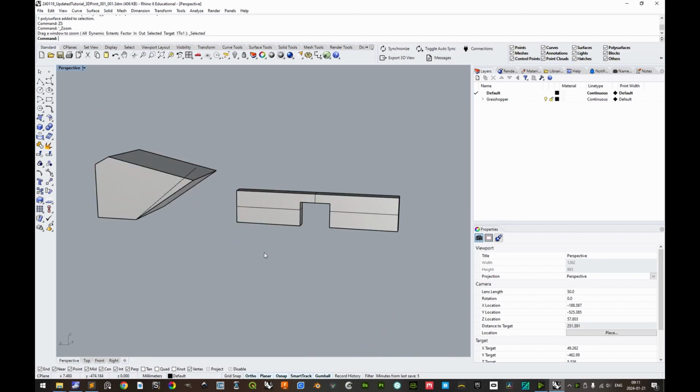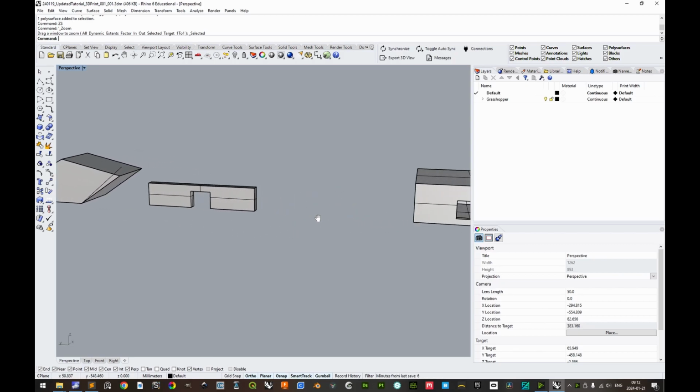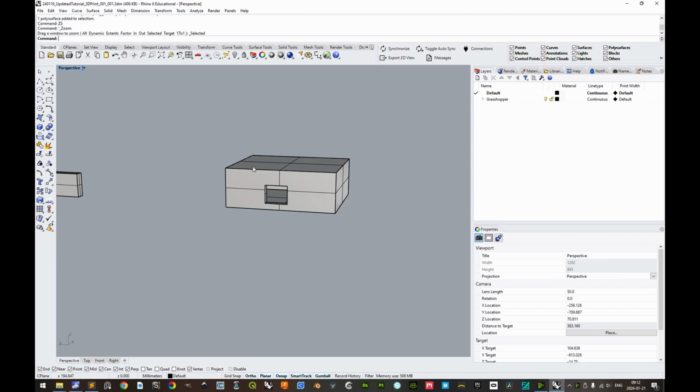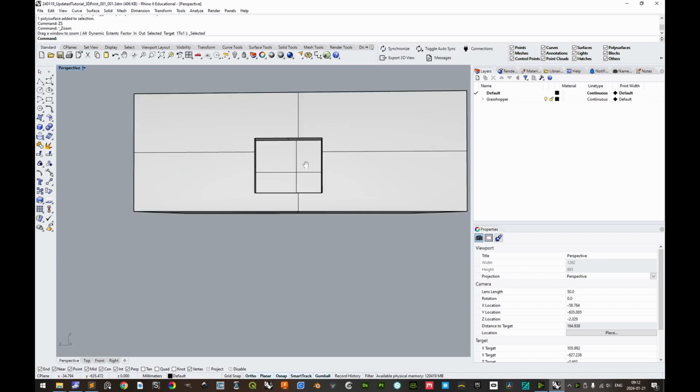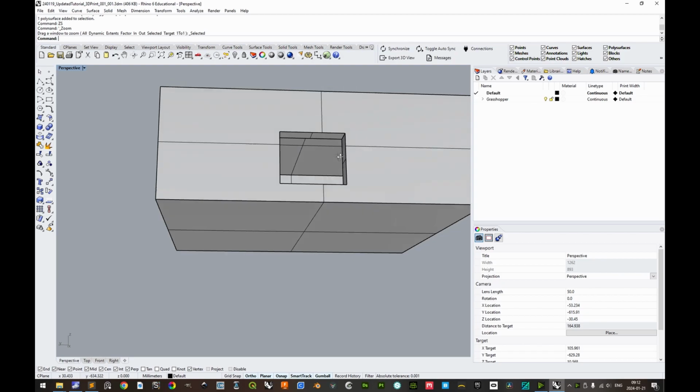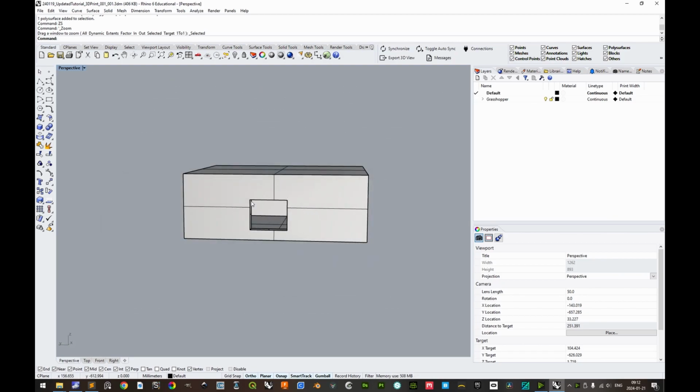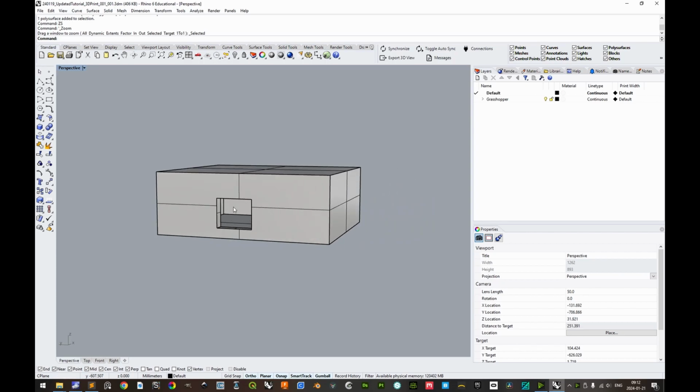Support geometry in itself is nothing problematic. It is automatically generated when we slice the model in the 3D printing software. It leaves the underlying and overlaying surface with a slightly less smooth surface texture and will have to be manually removed with a small plier, tweezers or something of the sort, but make sure that there is a physical possibility to actually remove the support geometry. The best example of what to avoid in this sense is an encapsulated void, which would definitely need support geometry underneath its horizontal ceiling, and where there would be very little physical opportunity to reach a tool within to remove these efficiently.